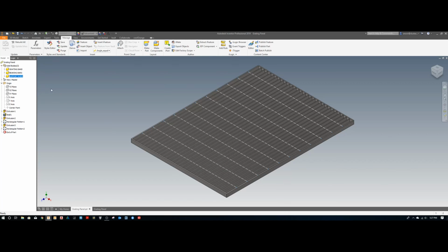All right, and the reason why it's always good to rename the solid bodies is because you may have a part that has 50 solids in it. And if you plan on importing all 50 of those into your assembly, well, it's probably a good idea to know what those solids are instead of trying to figure out, okay, what in the world is solid 12? Like, I have no idea. I can't remember. And you got to go back and hover over it and figure it out. It's always good just to go ahead and relabel all of your solid bodies like I've done here.